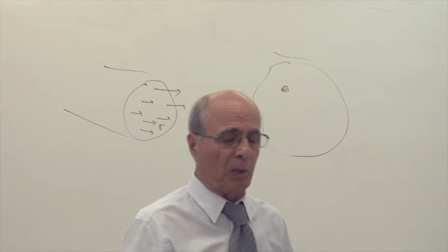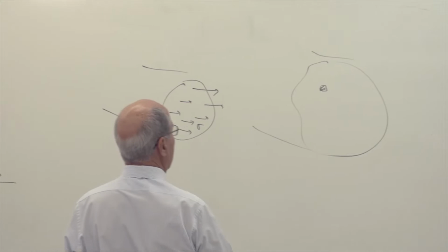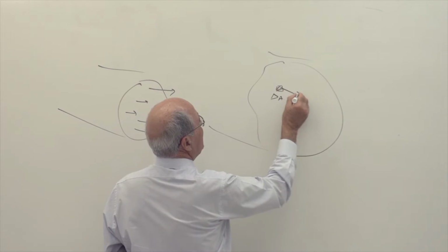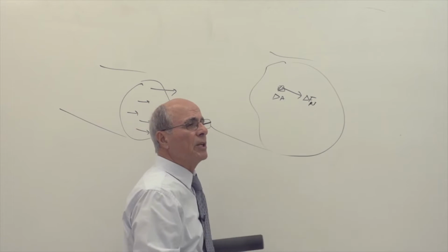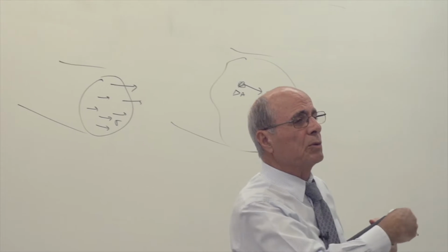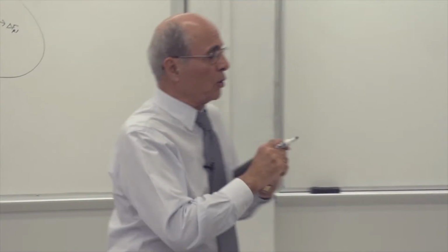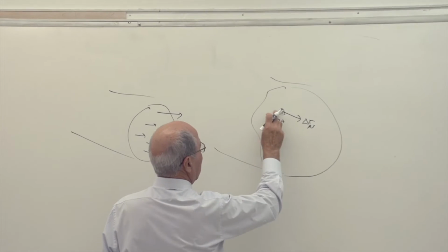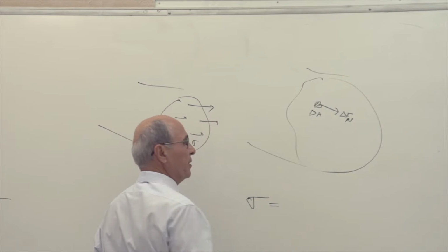It is in the book. You probably have read it or seen it, but I want you to understand the difference that we are going to have. So if this is dA, or little area, and then there is a force here, dFn, n indicates that it is normal to the surface, because when you get the force here, you have to break it into components, normal and tangential. Is that correct or not? Yes? So that part of the force which is perpendicular to that area, then we say again, sigma, the same definition. This is the general definition of sigma.